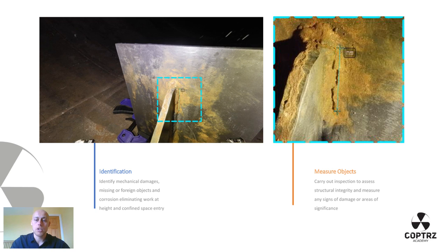And especially with the Helios 2, when you've got the actual measurement tool, you can find out the actual dimensions of cracks, deformities, whatever it may be, which is a really useful technique for a lot of inspection teams. They can go in and say, well, that is the size, it does need fixing, or that needs an extra weld. Let's get the welding team in to fix that.